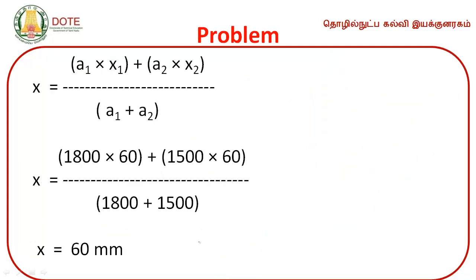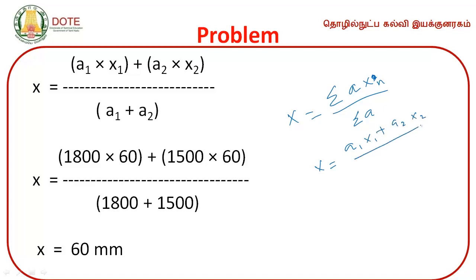Now we have to find x-bar and y-bar. x-bar is equal to the sum of area into x distance, divided by the sum of area. Here there are two components, two sections, so x-bar is A1 x1 plus A2 x2 divided by total area A1 plus A2.